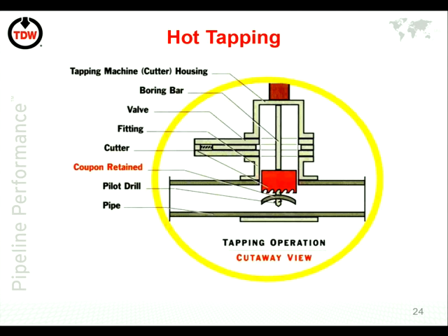It's all sealed. Then you start the drilling. And obviously, once you drill through this pipe, there's a release of pressure into here. And that will then fill with product, whether it be hydrocarbon or whatever, but it will be contained. It won't go anywhere because this is all pressure tested such that once the pressure is released, it will not go anywhere. Will you not equalize your housing with line pressure first? You can do that, and I'll show you how you do that a little bit later.